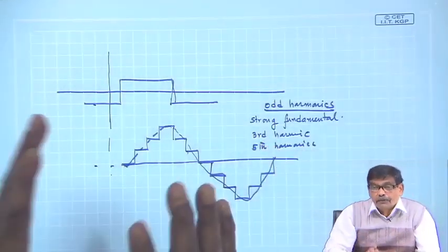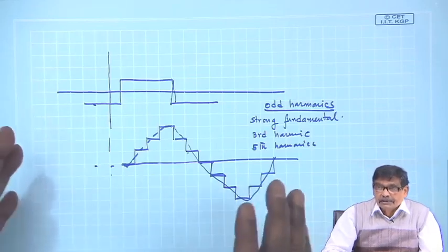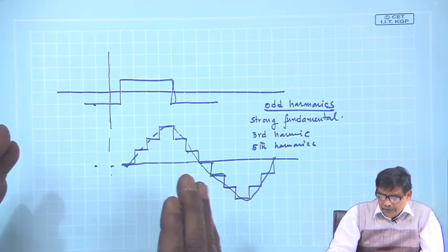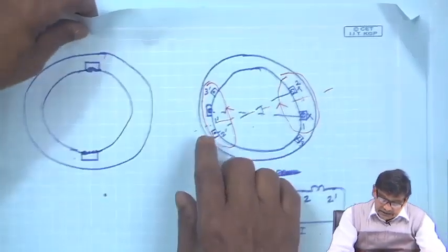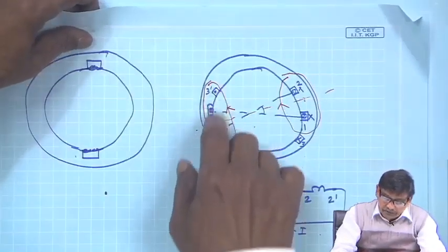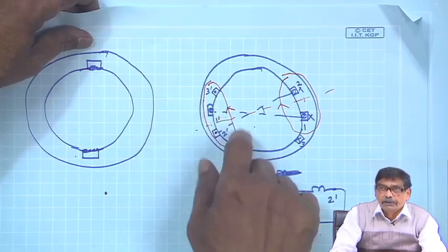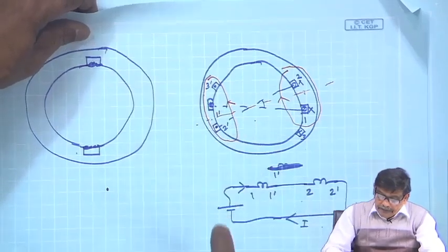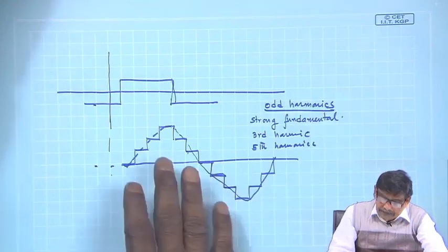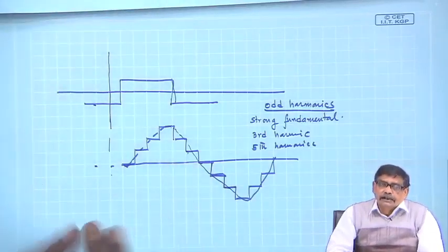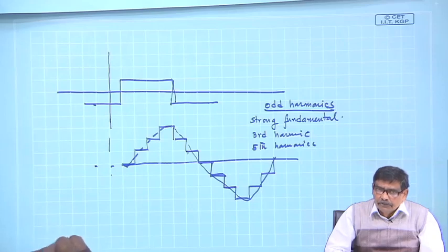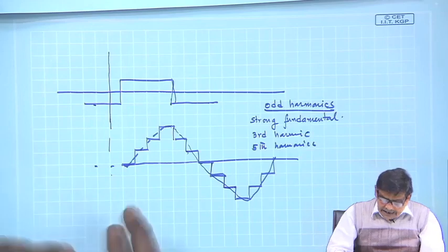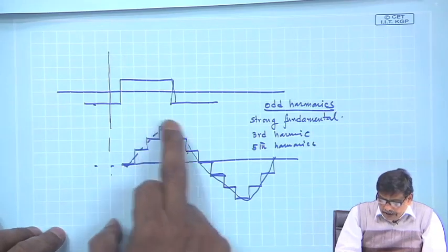One predominant harmonic at least can be eliminated by properly choosing the angle between two subsequent conductors of a particular group. Therefore, this is the thing what is done, that is, do not use a single coil, use distributed coils and get a stepped B distribution.